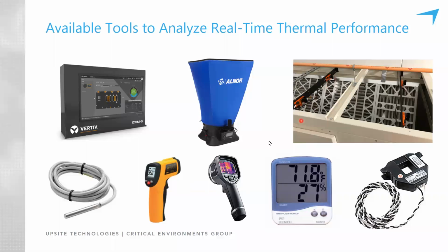You've got a variety of different temperature and humidification measuring capabilities, from tethered sensors that report back to a system you're looking at on a screen. You've got handheld infrared temperature measuring that have temperature gradients as well, like a FLIR gun. And you've got some temperature and humidity sensors that actually have local digital readouts in addition to what they can communicate back.